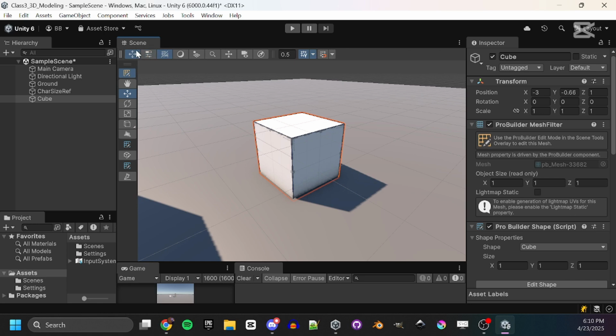In your main toolbar, the second item is called Tool Settings. In order to see these three things, vertices, edges, and faces, you not only have to click this thing, but this Tool Settings thing has to be visible. I can put that up here if I want to have it nearby. You can put it in the taskbar there. Now I can see that I have the ability to select these different things.